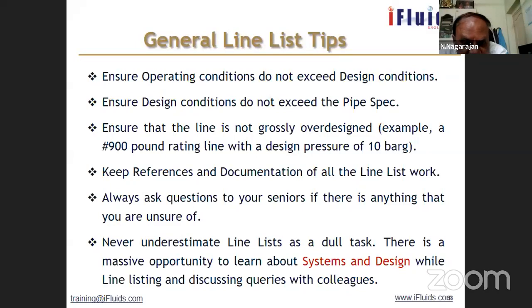Okay. Line list, don't underestimate. It's a dull task. It is a laborious task, but once you are able to make a line list yourself, you will learn a lot of things, because line list is connected with heat and mass balance, hydraulic calculations, piping material specification. So many documents are used as reference. So you will get to know about all these types of documents. You will have a full understanding of the piping system. So it's not a dull task, but it is a very good opportunity to learn about all the related documents.